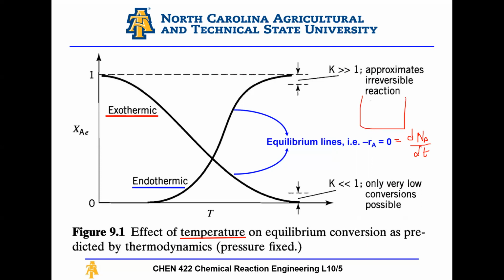So if I have a batch reactor, or a CSTR, and I'm introducing a feed, then when we are at equilibrium, the concentration of A is the equilibrium concentration. The concentration of A not changing does not mean the reaction is not happening. It just means that if I introduce 50 moles, 25 will react, and I will always have 25 moles left in my reactor, right? So this number of moles does not change. However, I still have a reaction happening throughout this process.